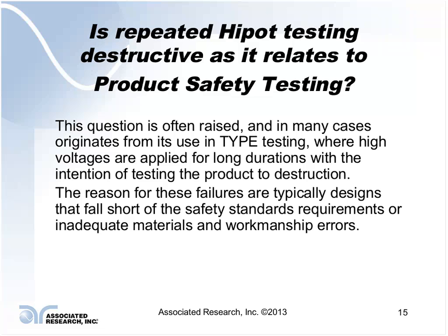We've done maybe a 100% Hipot test on that one particular shipment, to evaluate these things. As products are built, maybe in a sub-assembly stage, the product may be Hipot tested again. Now, once that sub-assembly comes in and is installed within your equipment, your equipment is tested again as a routine production line test at the end of the line.